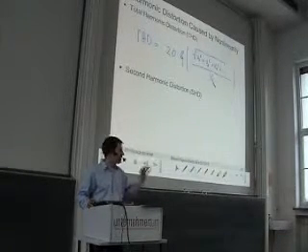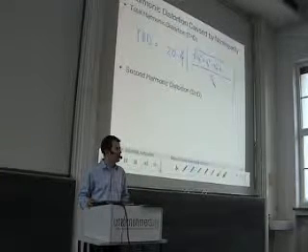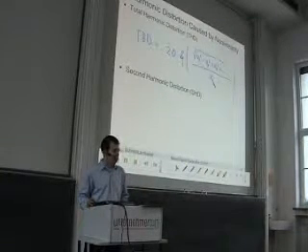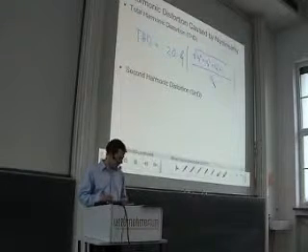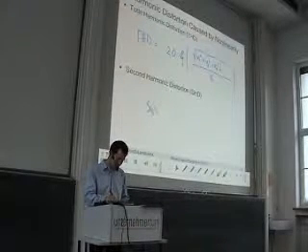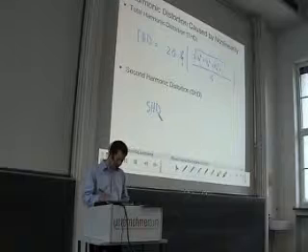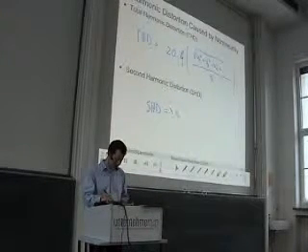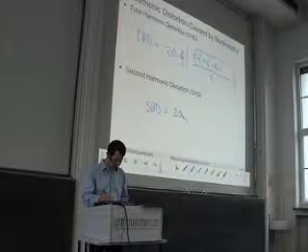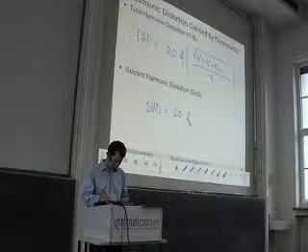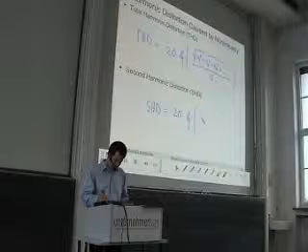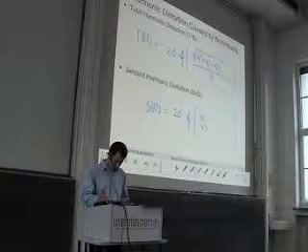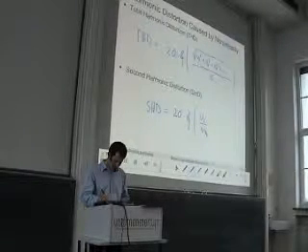Or if you say I'm mainly interested in one particular harmonic, then you can say, okay, for instance, I take the second harmonic distortion. Here I take only the second one, or third harmonic distortion is also possible. I give you the example for the second harmonic distortion, where we say, okay, this is only the second harmonic compared to the fundamental.